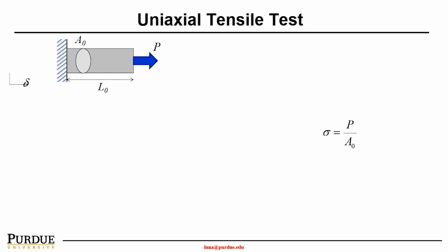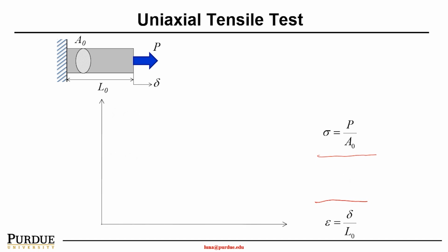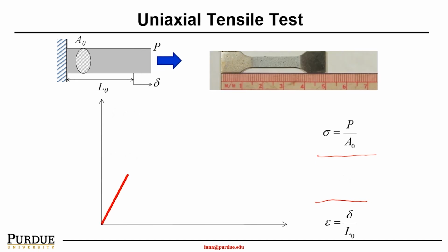Again, let's quickly recap what we learned in this class. We talked about uniaxial tensile stress testing. The tensile stress, sigma, equals the force over the area. The strain, epsilon, equals the delta L over L null, the original length. So we discussed the stress and strain curve, which is a very important material property